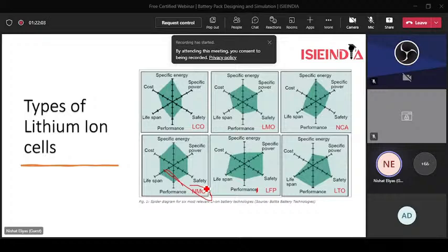It may be dangerous, as there may be a thermal runaway when using NMC chemistry. But it has the advantage of higher specific power and a higher charge rate. NMC has the faster charge rate.